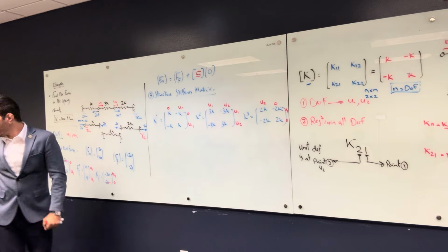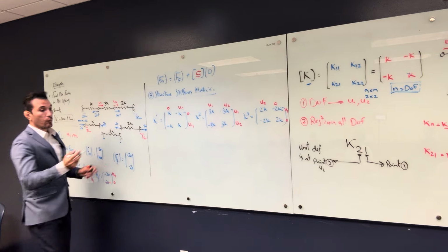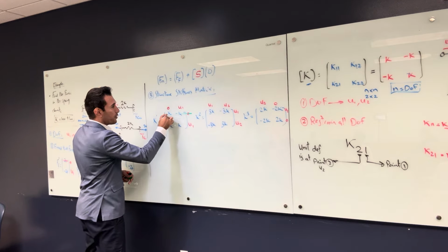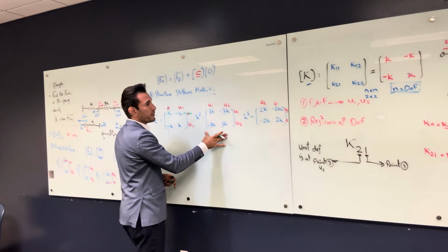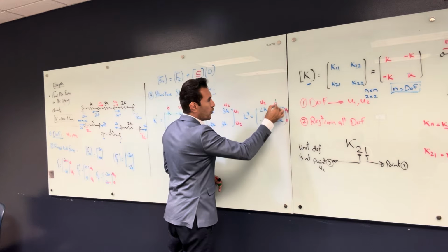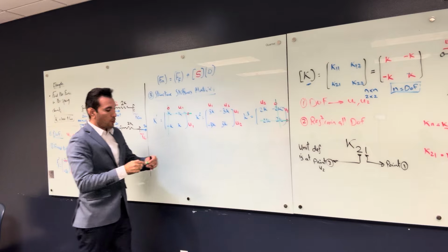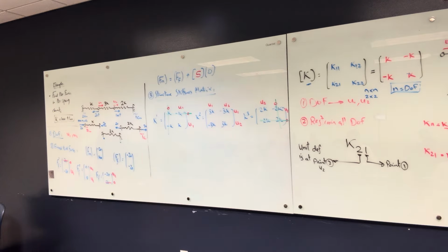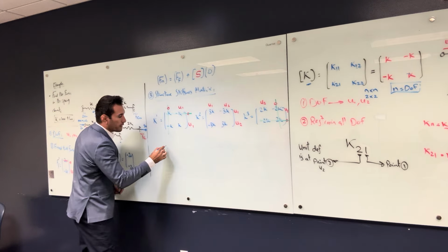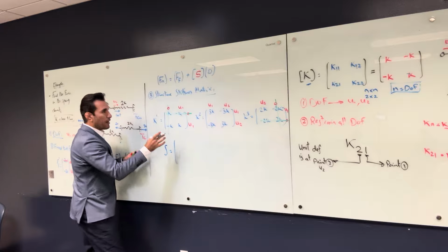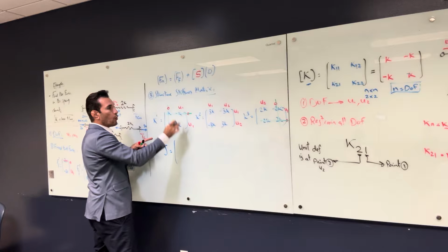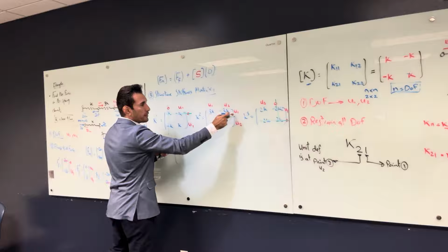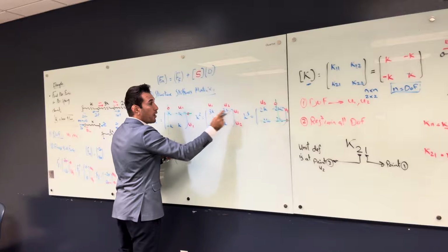So we are going to cross out the zeros where we do not have degree of freedom, so I'm going to cross this row. This whole matrix is going to stay. This one is going to be crossed. So what is going to happen now? I'm going to have a structure stiffness matrix where I'm going to sum everything that has U11. So U11 here is going to be plus U11 here.